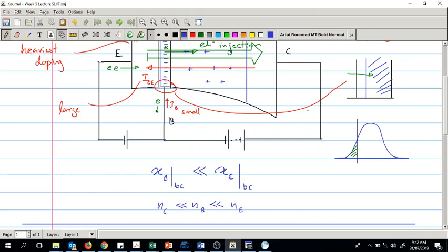In the active operation, current goes because the base emitter PN junction is now forward biased. But in the cutoff, base emitter PN junction is not forward biased. Let's assume that you disconnect the base terminal from the supplies, so base is not biased, right? Then you have a reverse bias junction to be overcome, which will not happen until you reach the breakdown voltage, the Zener breakdown.